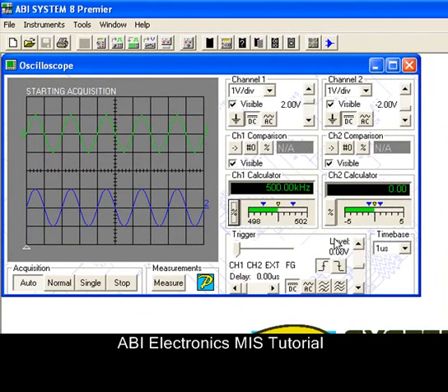Back in the oscilloscope, signals can be triggered on channel 1 or 2, an external signal or the internal function generator. The rest of the trigger section includes trigger level, trigger slope, trigger delay and trigger coupling. Finally, the time base, including extended resolution sampling, can be set here.